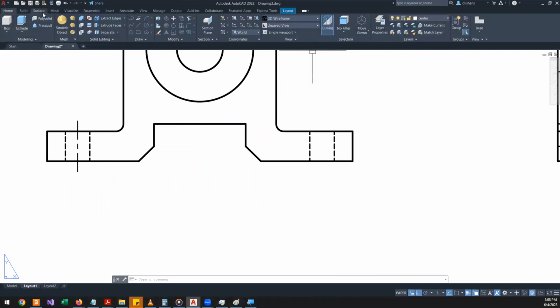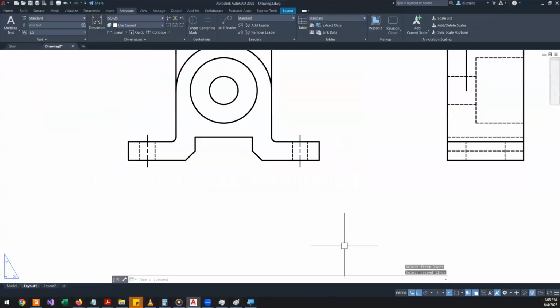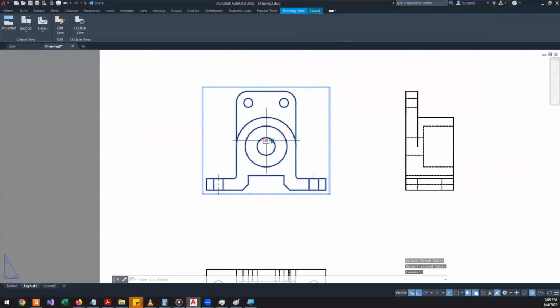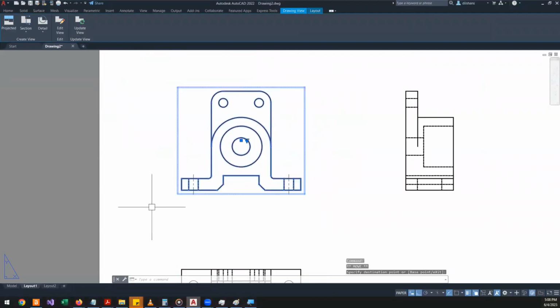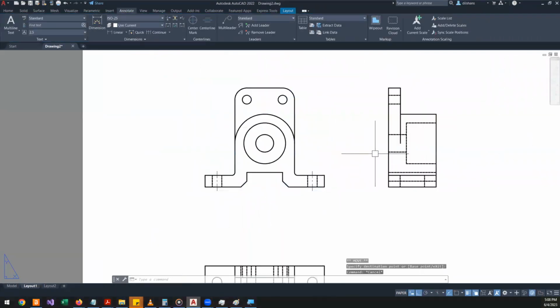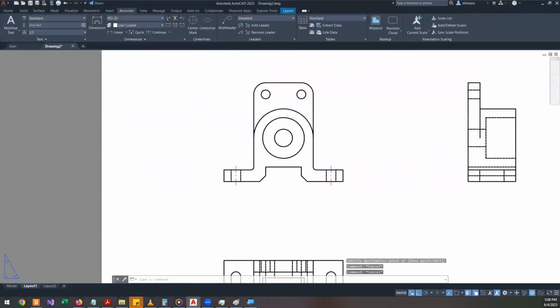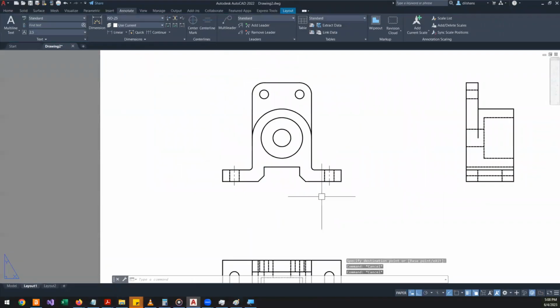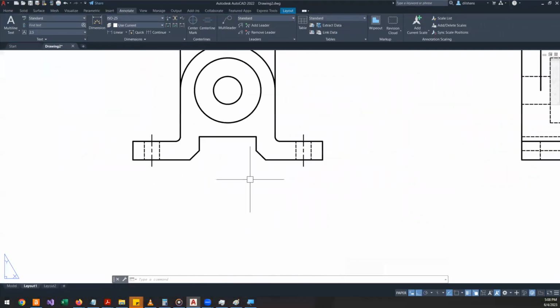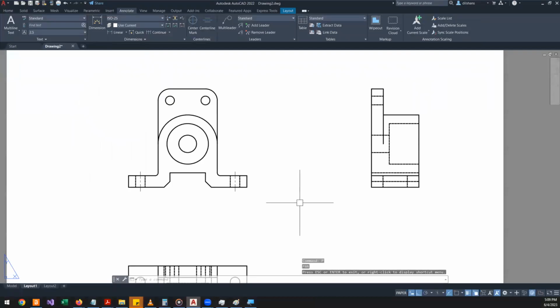Okay, so go to edit and select the edges to where you want to apply the center. Another nice thing about this is, when you move the view, see, the center lines also follow. I mentioned during the 2D drawing part that there is another practice of applying center lines onto the layout. So that is what I was talking about. Everything will be properly connected.